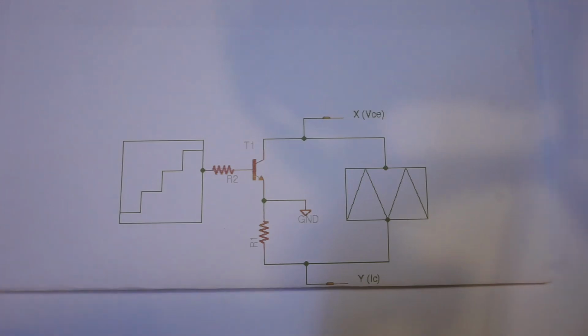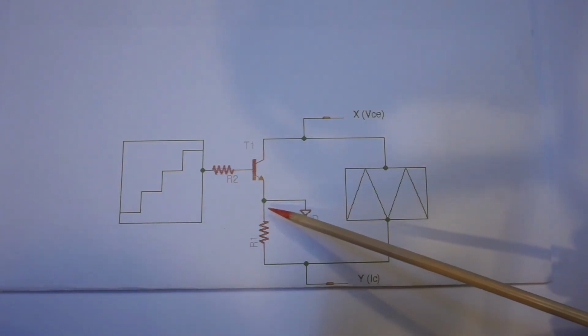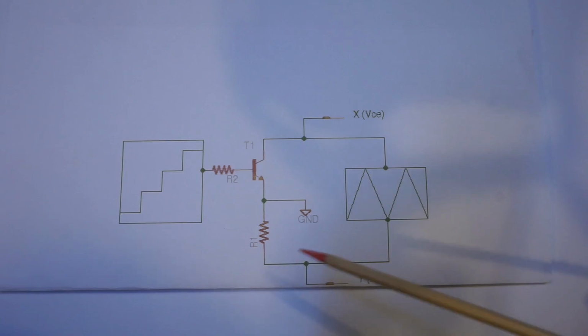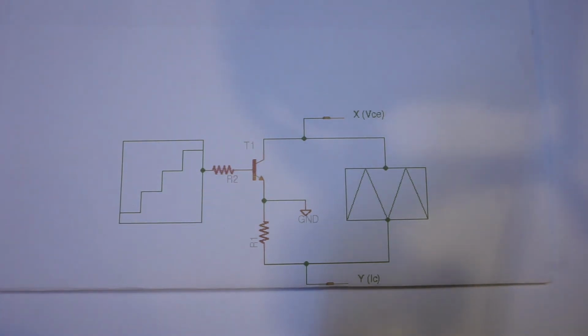With the approach we mentioned earlier, you can see that the current measurement for IC is actually negative with respect to the oscilloscope ground. But on most of the scopes, you can easily flip the vertical so that the resulting image looks the way you expect it to be. Anyway, for the rest of the video, I will stick to my original approach as shown here, as I have more control over each of the signal sources and can adjust the offset of each very easily. And towards the end, I will show you briefly what the curve looks like using the alternative approach.